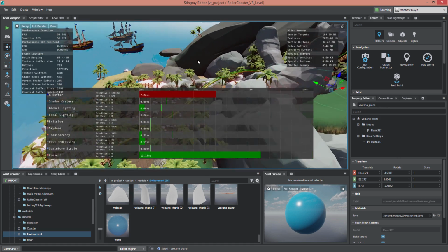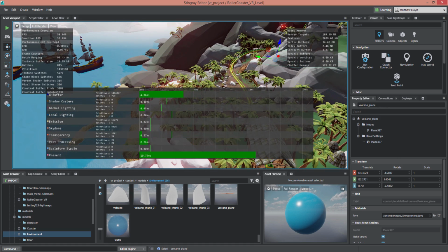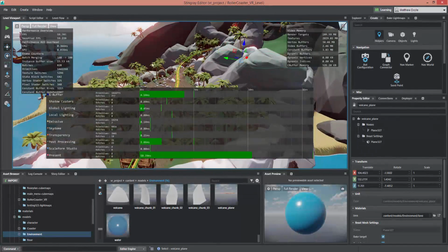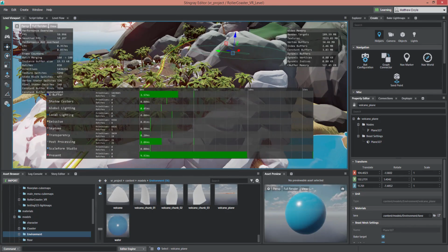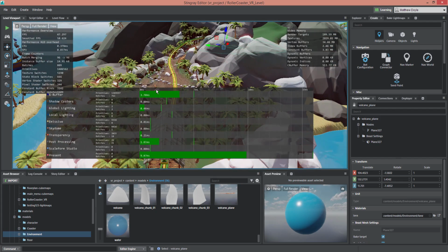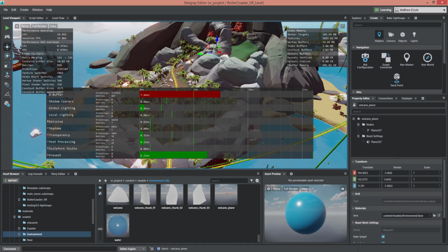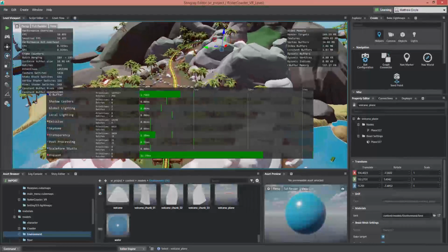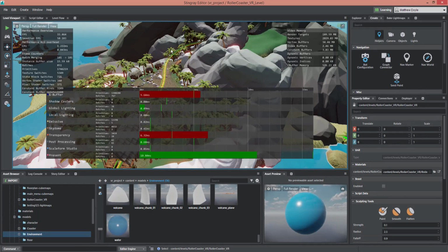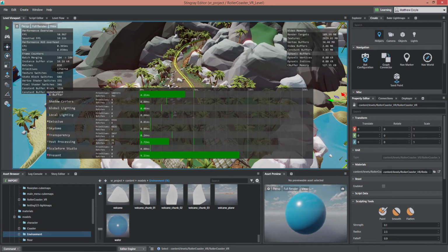So you can see here as I'm rotating around, the G buffer is really kind of spiking pretty high. And that's because there are a lot of objects in this scene, and the poly count is not super high, but obviously high enough to cause a spike when we really zoom out here and rotate around. So maybe if I wanted to make some tweaks, I would make tweaks to the actual geometry itself. I would create some LODs for my objects so that they show less detailed versions as I'm further away. I could maybe reduce some of the amount of objects I have, or even combine objects into one object, and that would help with my G buffer, bringing that down some.